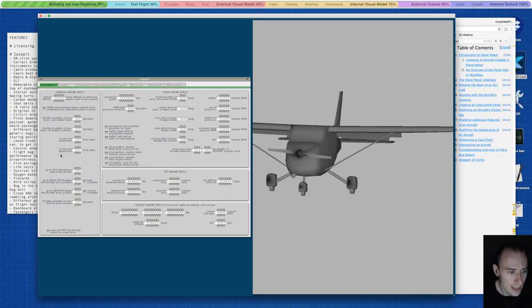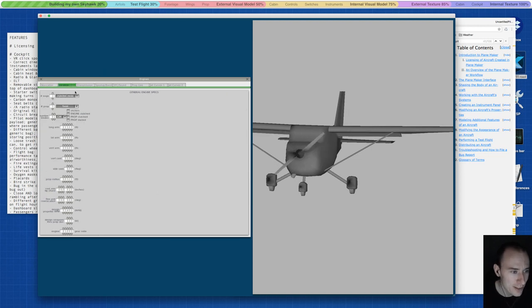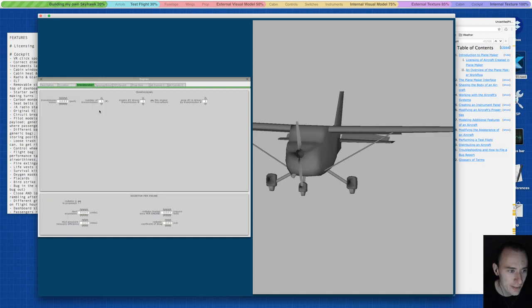Critical altitude 0 is sea level, that's good. Oh yeah, high idle fuel adjustment and stuff. I don't know, never found anything about that. And again, this is something that I guess I need to set based off of my test flight to look at my fuel flow and stuff. So this is not set, but I can only set it through test flying the thing. 2700 top of green arc. Minimum, yes. Governor we don't have. Ratios, we don't have jet engine or rockets. Injected, reciprocal engine, yeah. Man, we did some searching. Design airspeed, roger, it's all good. No transmissions.